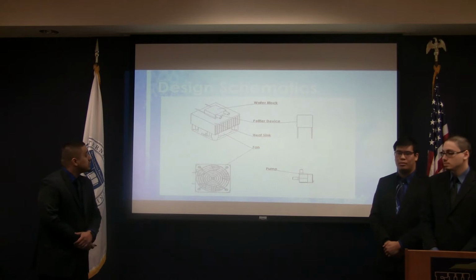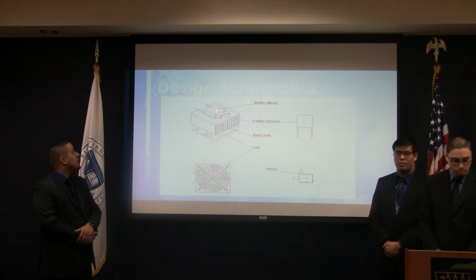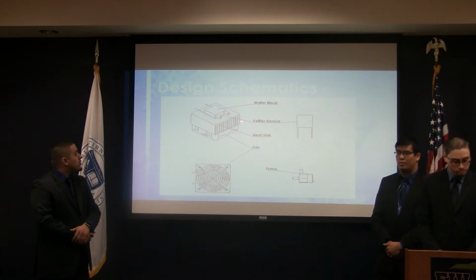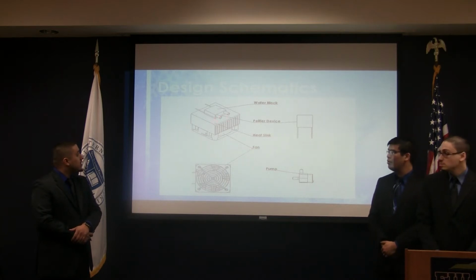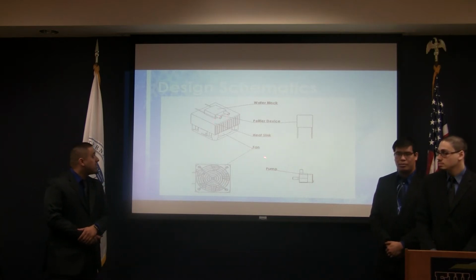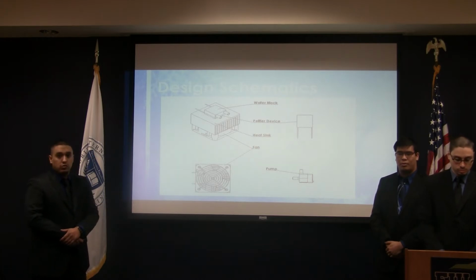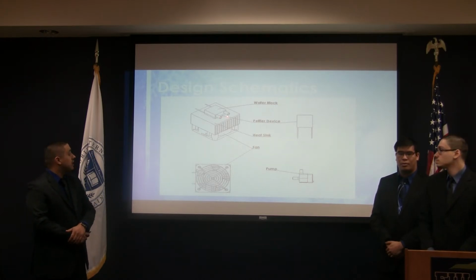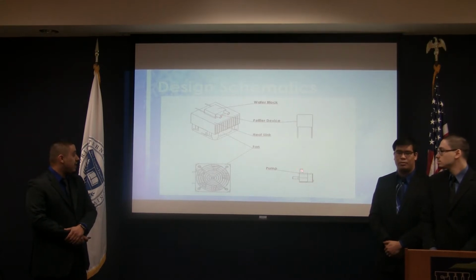Now, as far as cooling is concerned, the cold side of the Peltier will be touching the water block. The water block will get chilled by the Peltier, and water will be circulating through it in a closed loop of vinyl tubing through the inlet and outlets of the water block, as you see here, into a submersible pump, which will have inlets and outlets here.